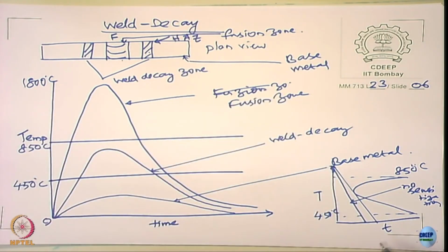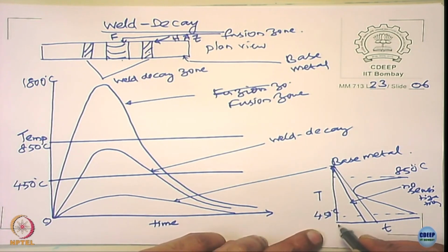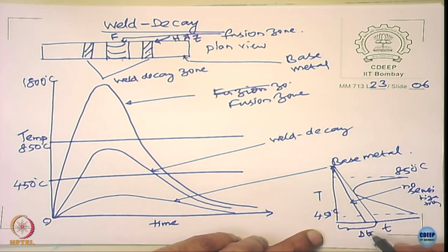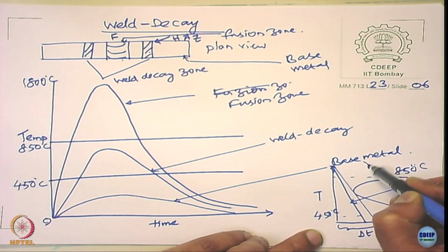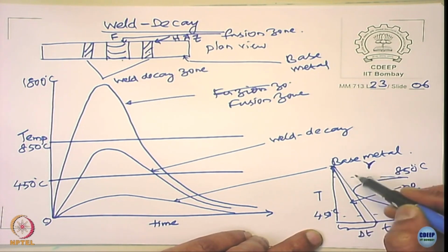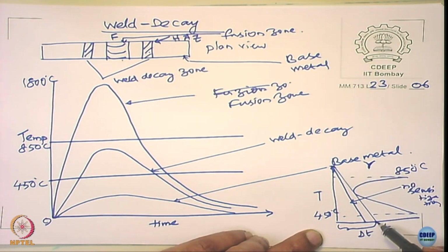Okay. Look at this. This is the maximum time that is allowed for the material to cool down. When you hold it in the gamma regime, this is what is called the gamma regime. This is the maximum time allowed to cool. If you go beyond that, what happens? Chromium carbide forms.